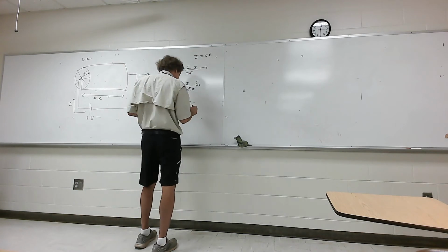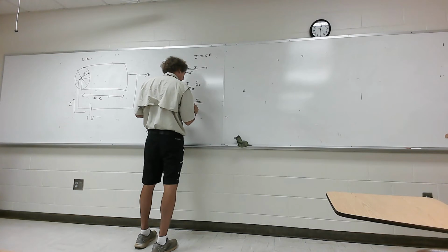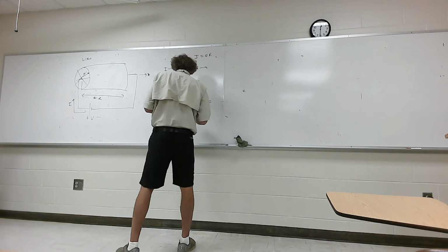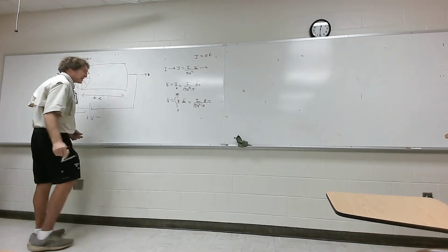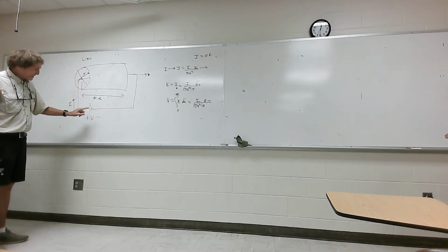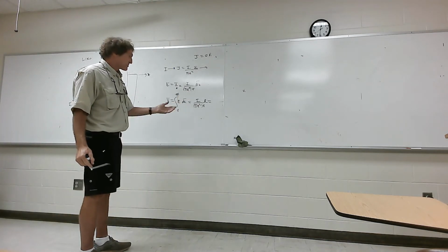So this is equal to I over pi a squared, divided by sigma, times L, the length, and that is the voltage. That's where I started with I, assumed I, and ended up with V in terms of the actual value of I and the geometric parameters.